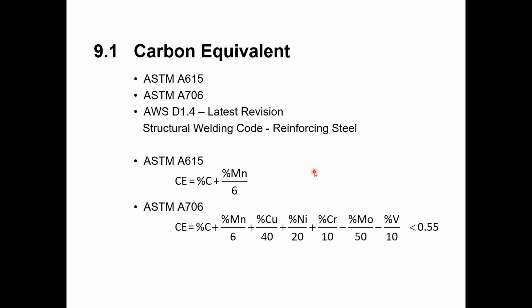And what I mean by that is you have to assume that it has a carbon equivalent over 0.75, which means if you're going to be welding it, you have to preheat it to 500 degrees if that information is not made available to you. So it's important that you know what information is being given on your mill certs, that you know how to use it, and that you know what the implications are of your different production processes. We don't ever, especially with our reinforcement, want to cause issues that might embrittle it and cause an abrupt failure that is not predictable.